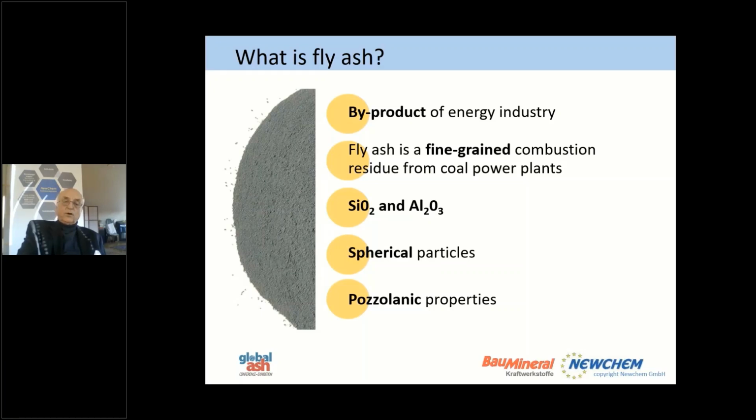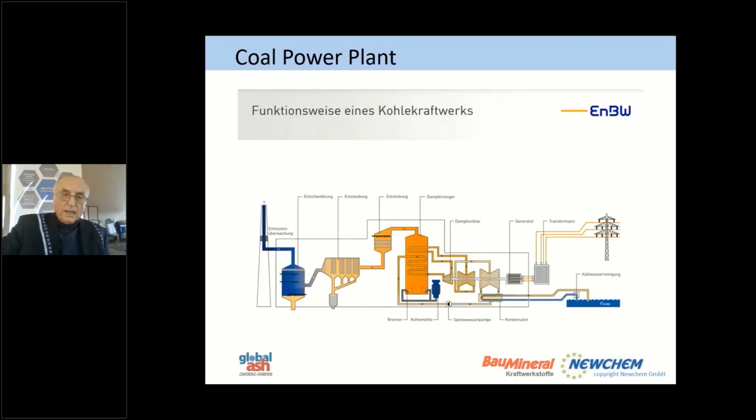Much more important also is that they are spherical particles compared to metakaolins, which are platelets, and they have their pozzolanic properties. Now, compared to what we heard this morning, we are taking the fly ash away in a continuous way from the coal burning plant.